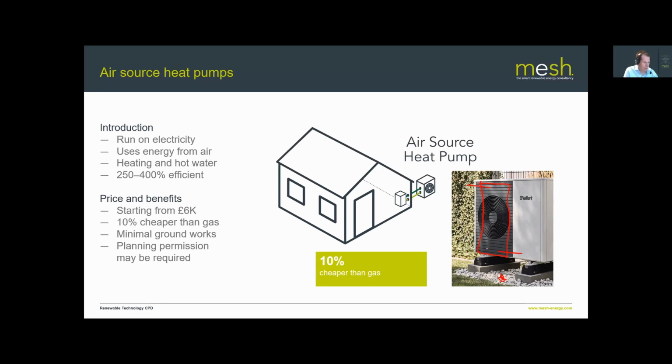So this down here is going to be about -30 degrees C, and by the time it reaches here, it might be at -15 or so, and you're extracting heat. Obviously, if you chill air by that amount, then you're going to get some condensation on the evaporator. Depending on the humidity on the day, about every 20 minutes or so, the heat pump will have to go through a defrost cycle.